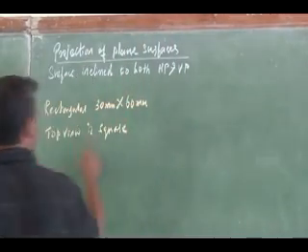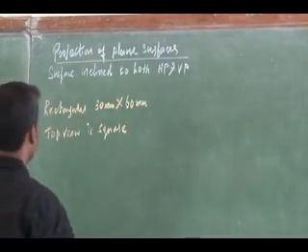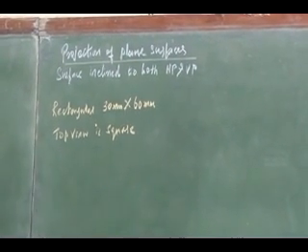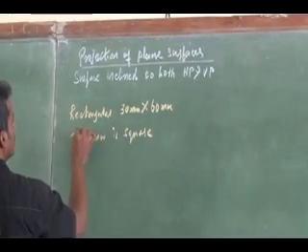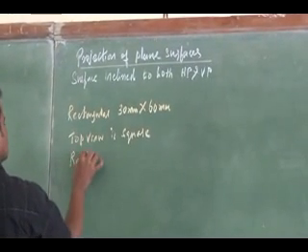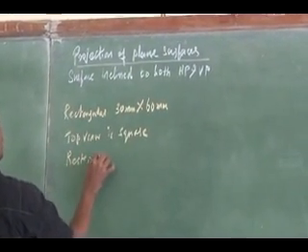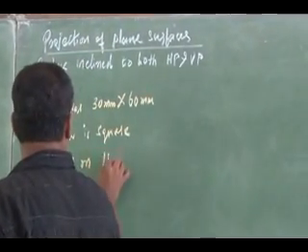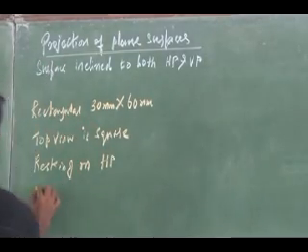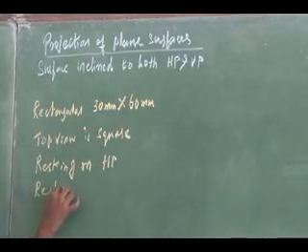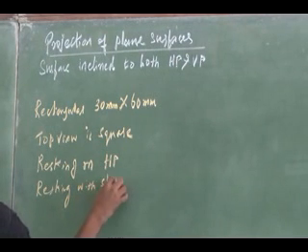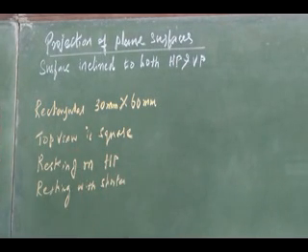The top view is a square. Then the given data is the resting edge. It is resting with a shorter edge. Resting on where? Horizontal plane. Make a note, hint of this: resting with shorter edge. Shorter edge in the sense it is 30 mm edge.